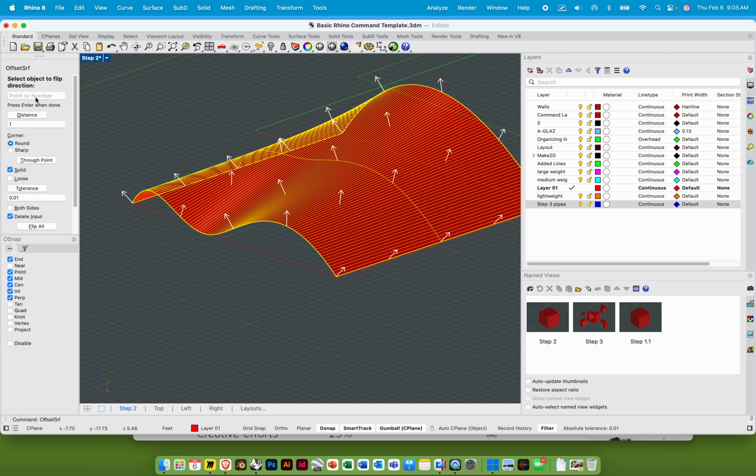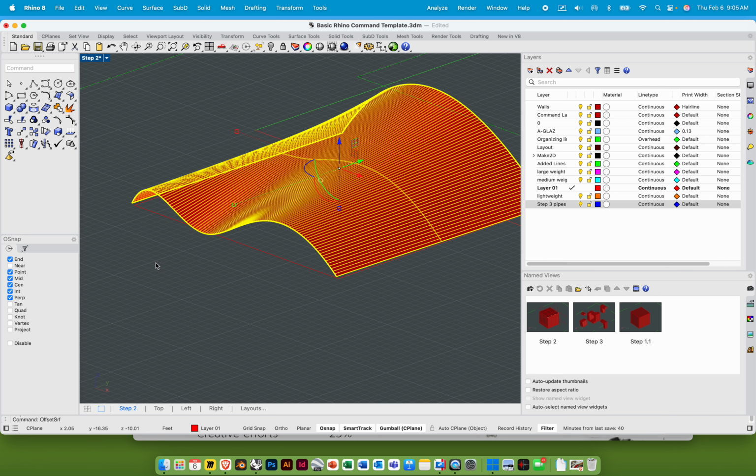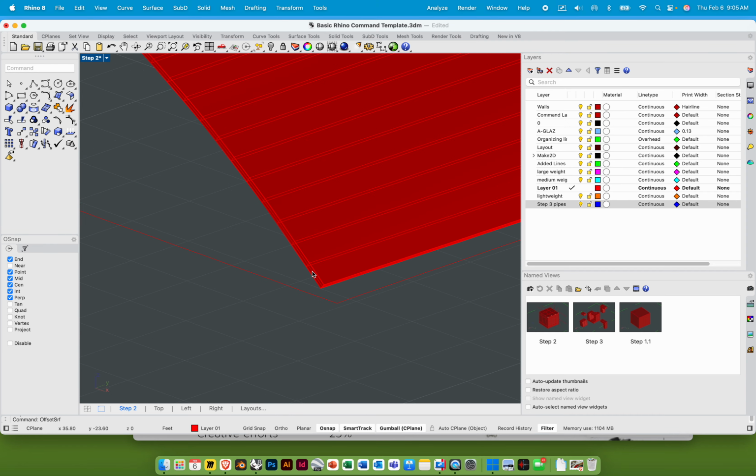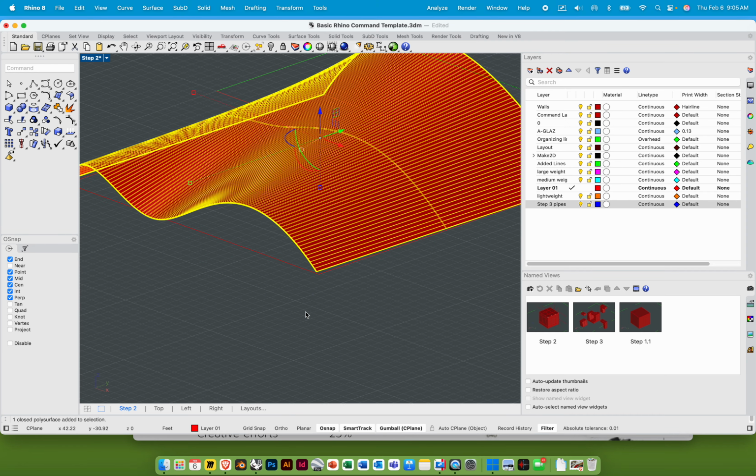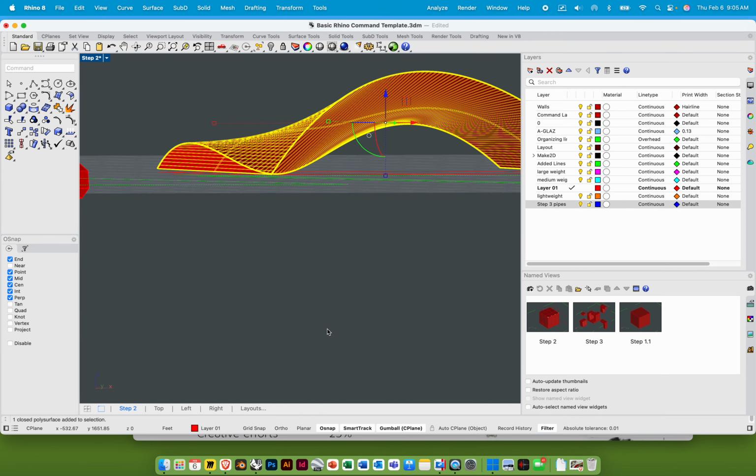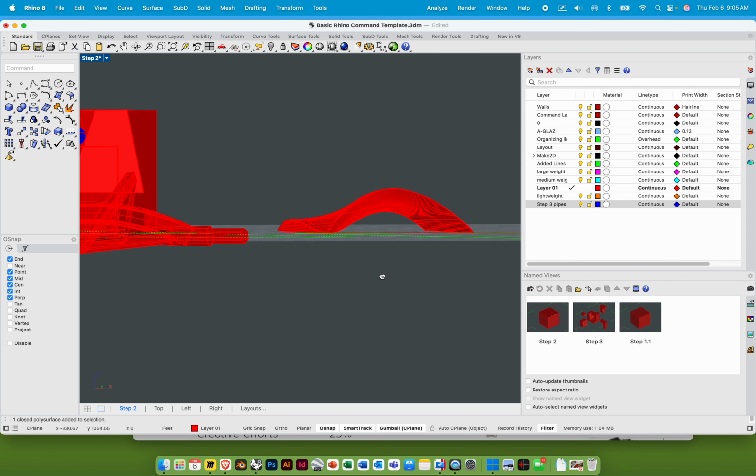Maybe I want it to be very thin, and I just want it to be a distance of 1 inch. So I'll type in 1 inch, enter, and I'll make it a very thin surface, right? In my case, it got those numbers. Awesome. Enter again. And as you can see, it's a 1 inch thick surface. Pretty sweet. That I can Boolean difference because now it's technically an object.